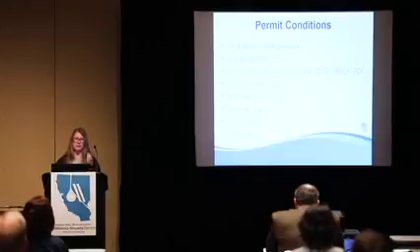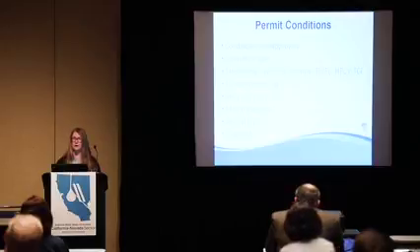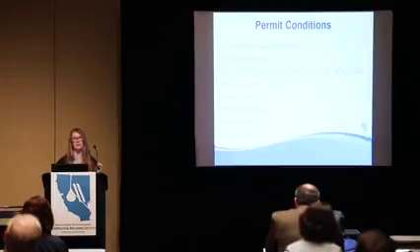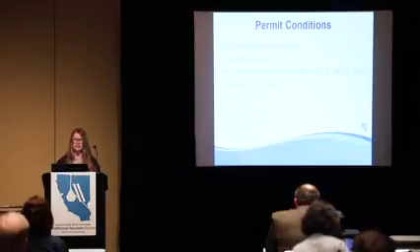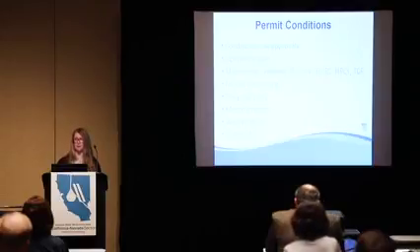One unique requirement of the permit amendment was an annual report. We just submitted the first of those for our systems a couple weeks ago. The annual report is meant to describe any issues that we had with the treatment, if we had to do any GAC changeouts, if we had premature breakthrough on the carbon, to describe any issues. That was kind of interesting, and I think it was well received by the district DDW office. We did receive some good feedback on that. And so that is now a permit condition for us. We will be required to submit those annual reports every year.